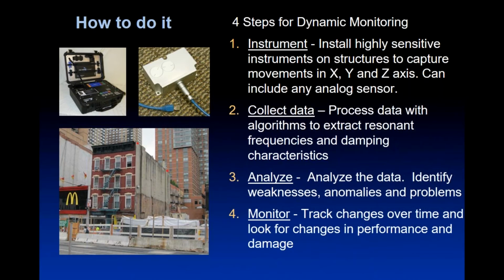Let's take case 1, and we're taking measurements of damping and frequency off a building as it is. We've got the ratio of displacement per unit force. If we then look at the code and the expectations from the code of force and displacement.